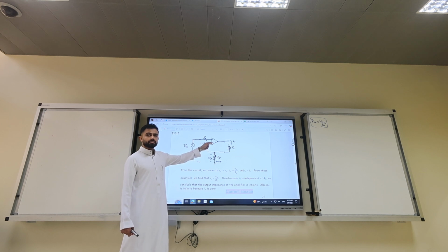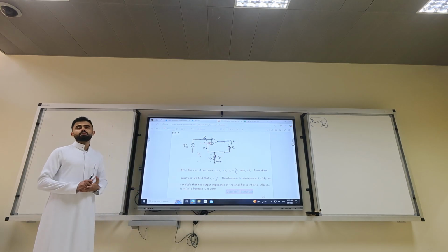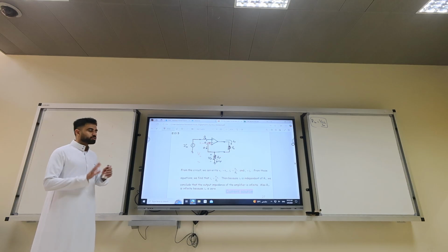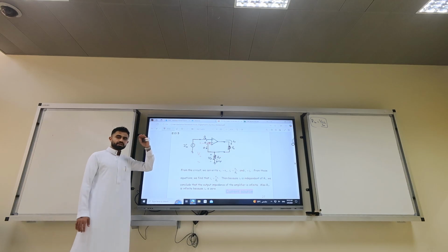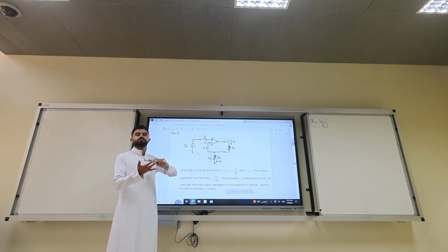Is it always that the negative side is V input? No. Not always. Don't generalize with op amps. You have to play with the rules. The rule says the first step is you have to know if it's inverting or non-inverting or both. We know it's non-inverting. Second rule, check the negative feedback.